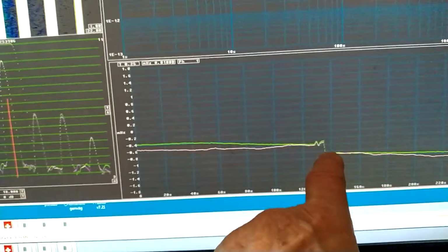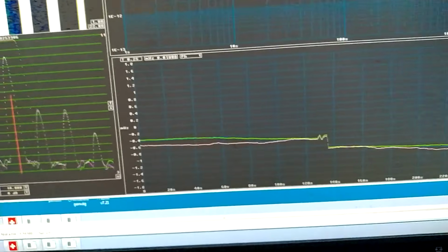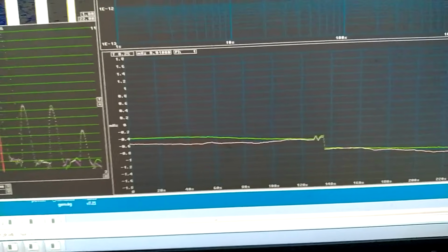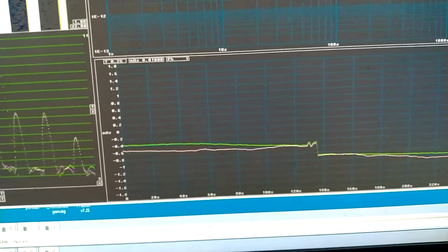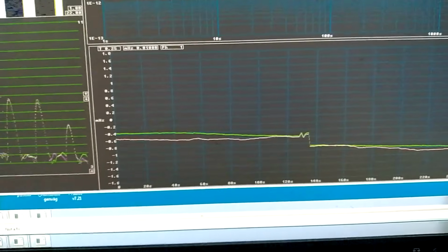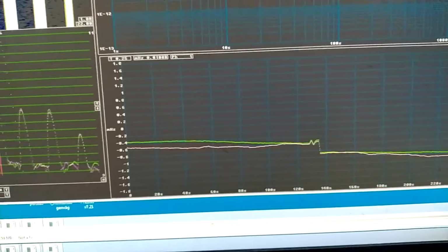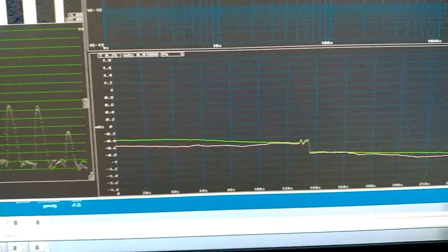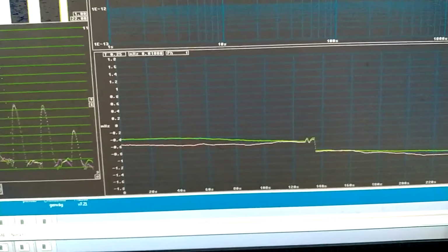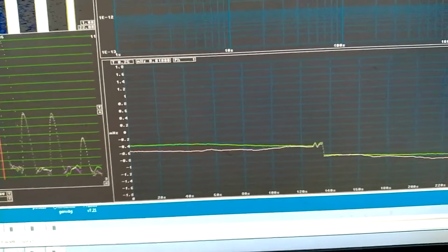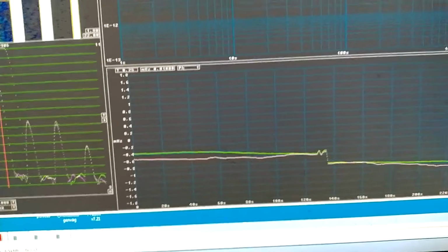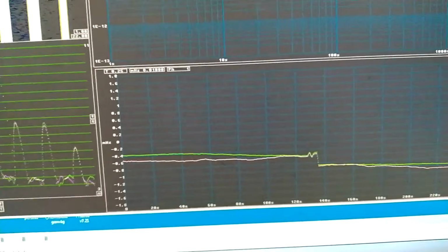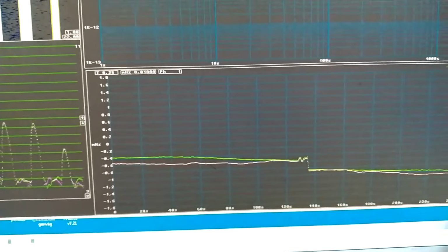But at this point, there is a frequency jump that is the same in both channels, which means it comes from my oscillator under test. Now, this isn't really harmful for the intended use because it will come in only one channel, and if it occurs seldom enough, it will not matter. Because it's not in the other channel, so it will not give a correlation result.